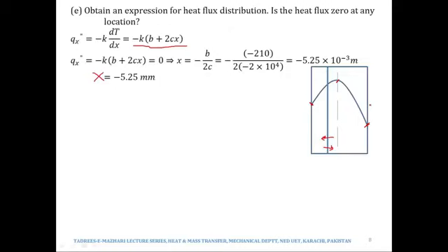When we started solving the problem and the temperatures at the two faces came out to be different despite having the same T infinity of 20 degrees Celsius on both sides, that was the very first indication that the medium of heat generation is not placed at the middle, since the curve was not symmetric.